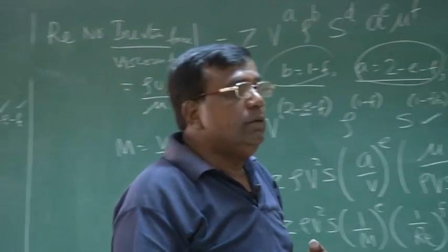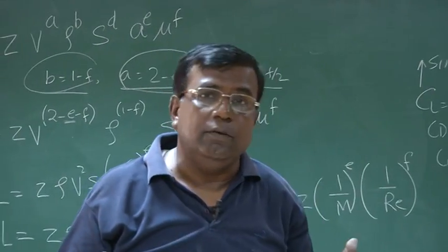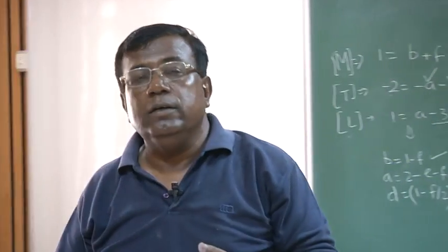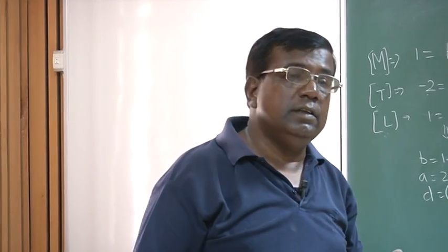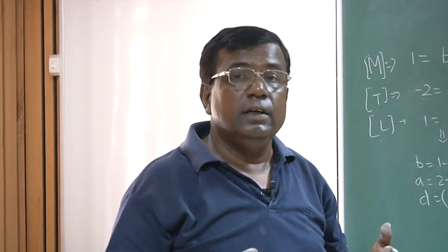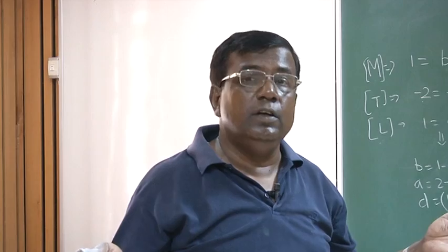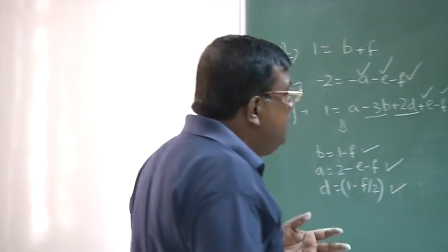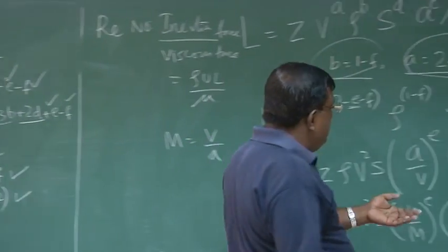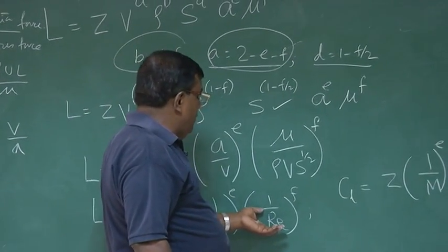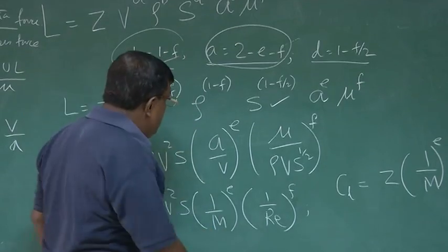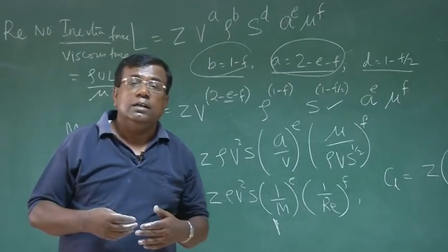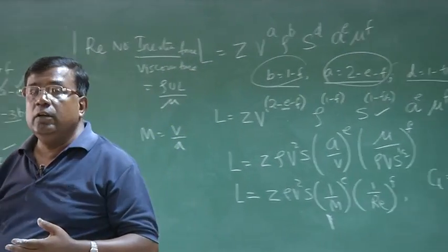If I want to get the pressure distribution over the aerofoil or the wing, it is important how viscous the flow is. If it is highly viscous, that will have a larger effect on the whole redistribution of pressure through shear stress and all. So we got very important non-dimensional parameters called Reynolds number and Mach number. Mach number is important for compressible flow when the speed is near Mach 1 to more than 1.